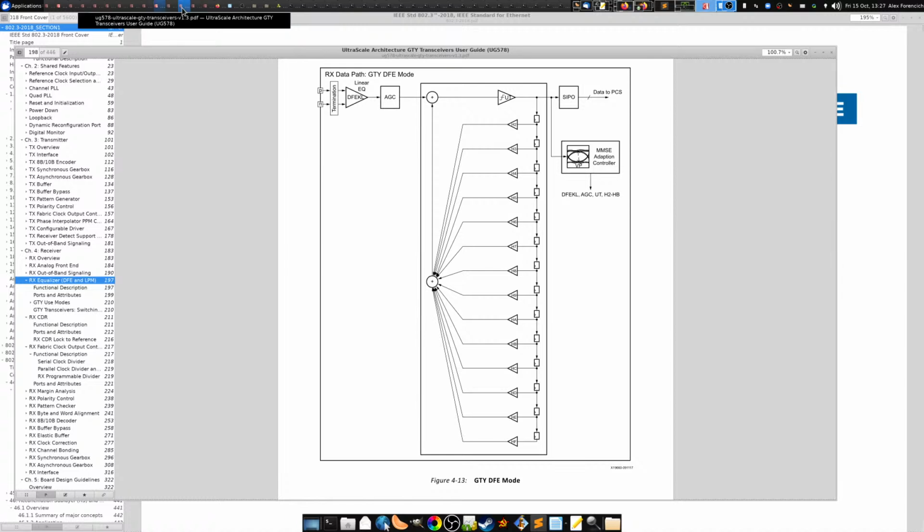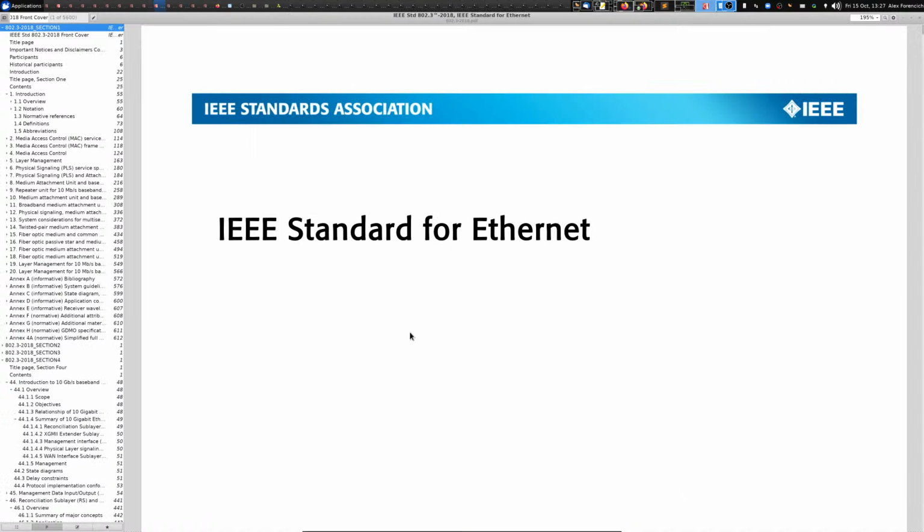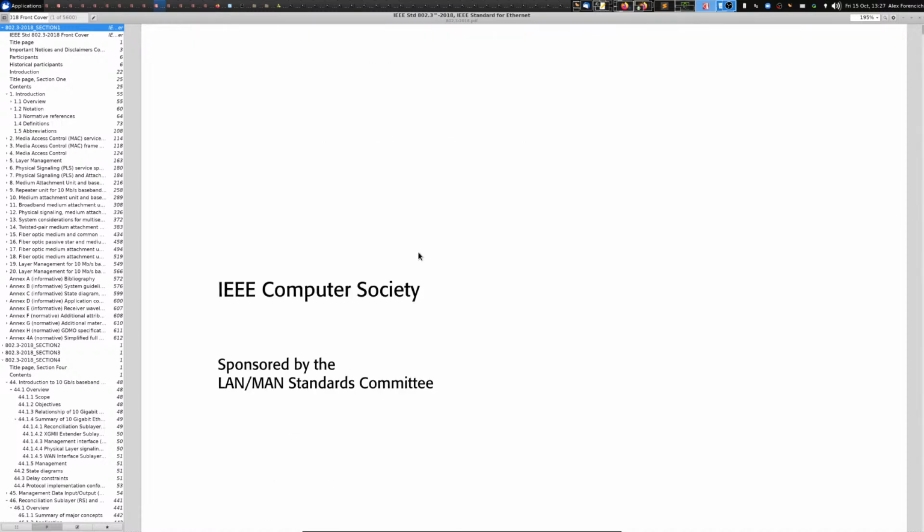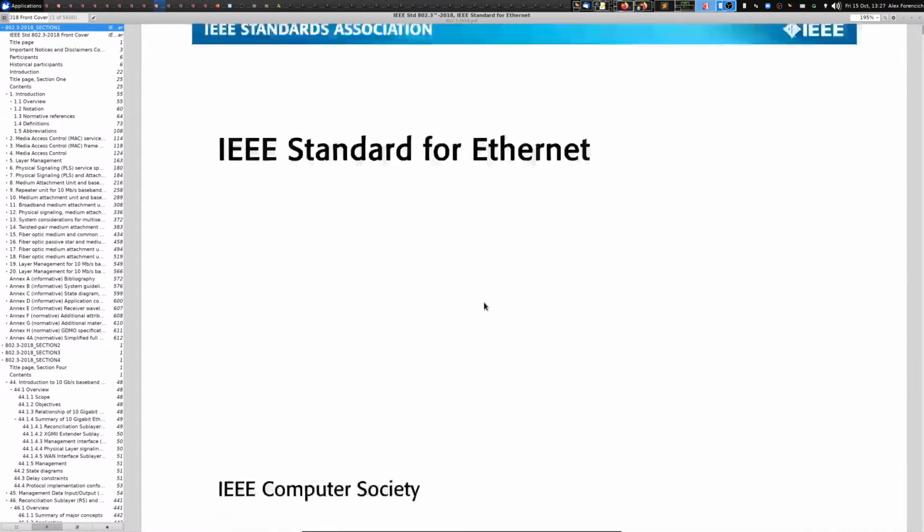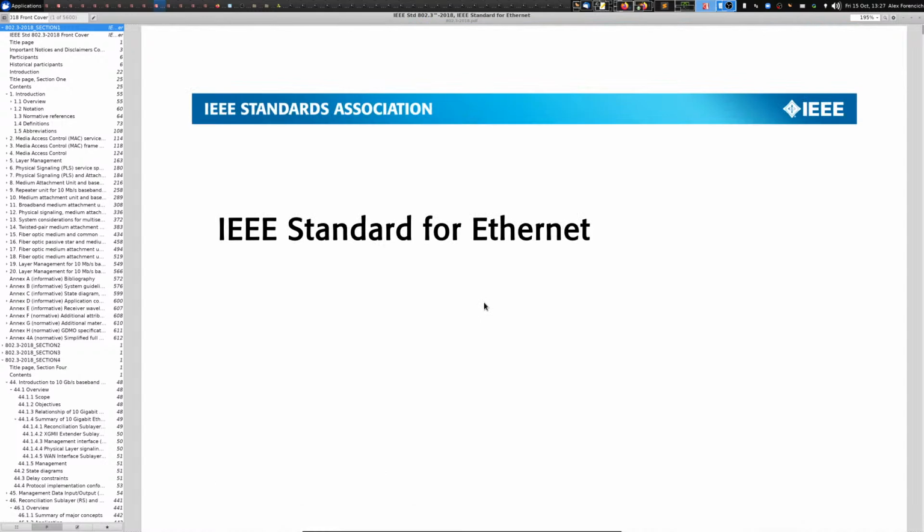And it basically just ends up being protocol dependent. So what you need to do is be able to look at what's coming down the link and make a decision whether or not the link seems to be working correctly. And if it isn't, then you reset it. All right. So to get an idea for how to do that, what we need to do is take a look at the Ethernet specification, which talks about exactly what's going on over the link. And with that information, we should be able to come up with a method for resetting the transceiver based on what's coming out of it.